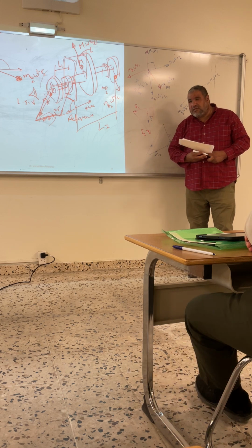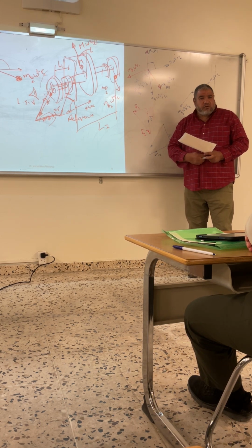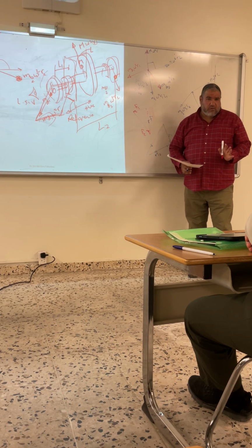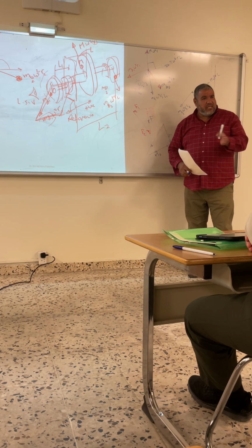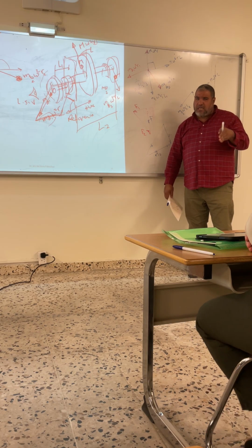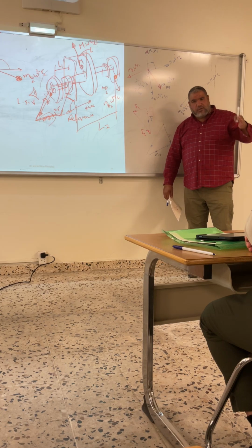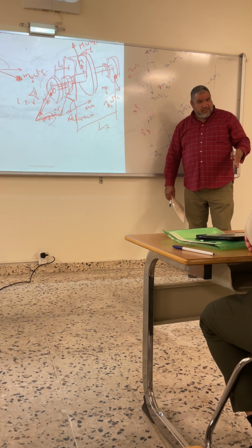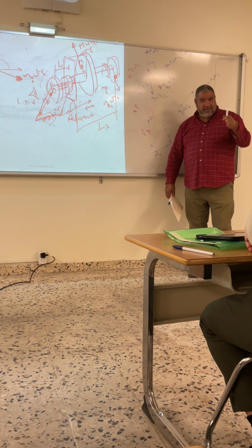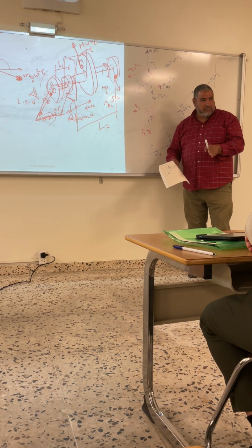This is the end of the story. Whenever you start the business of the dynamic, first of all, you have two ways to go. Either you list down everything in a table, and usually we start with the table by writing down 1, 2, 3, and then the balance, the mass itself. And then you put M1, M2, M3, R1, R2, R3, right, guys? And then the angle theta, remember? And then you take cosine theta, sine theta, because you decide to go for analytical solution, right?